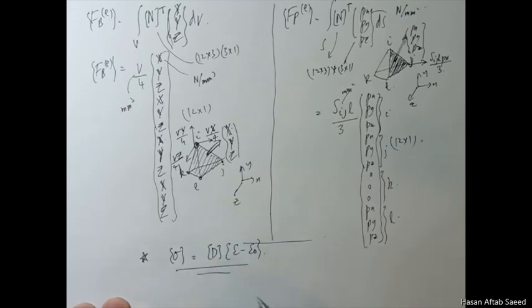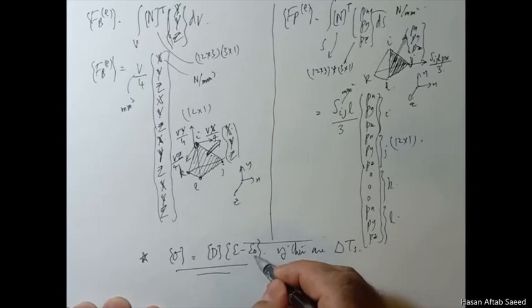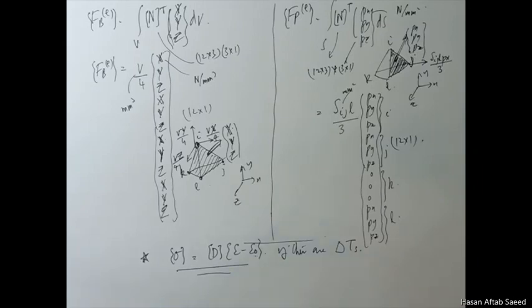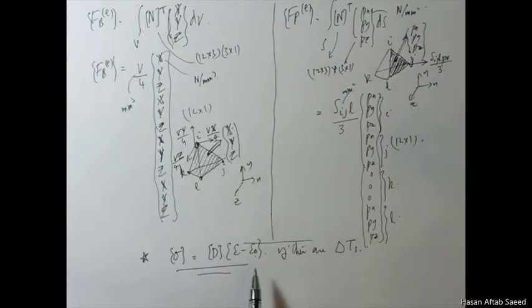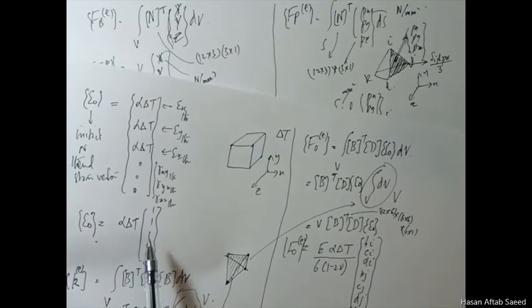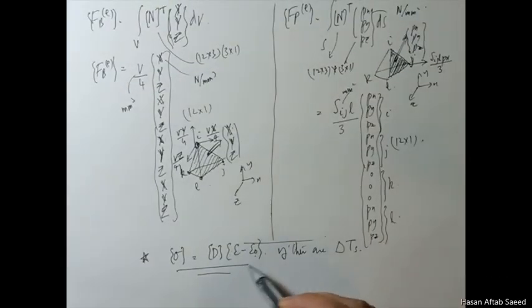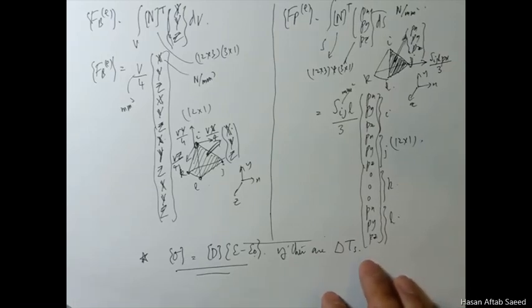it in this form if there are temperature changes. And this expression, this you know, is simply this one. So whatever total strain vector you get, you remove this part and you get the mechanical strain. And once this is the mechanical strain, then you can get the stresses. And if there are no temperature changes, obviously this becomes 0, so then there's no issue. So that's the end of this lecture. Thank you.